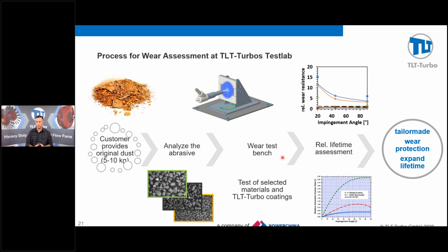Sometimes it has to do with a test bench, sometimes it just looks at the chemical composition of the environment, and you realize it's a very corrosive environment, so a material change is needed. So the environment will drive the material. We'll design a material that'll handle the structural strength needed for the rotating equipment, and that becomes the new material in the fan system, avoiding the corrosive environment.